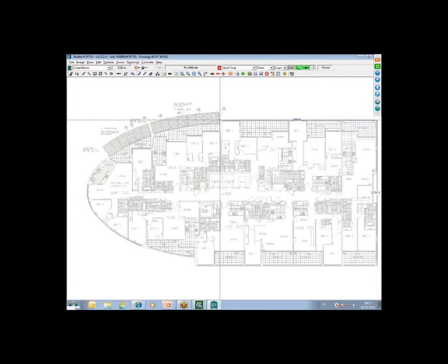I'm going to do this very quickly, and I'll just click on that line first, on that point there, and put in what the dim is on that line, and then select the vertical line, and that's just clicking on start, clicking on the end, and putting in the dim of that line. By doing that, you automatically calibrate each line that is displayed on the drawing. So it will accurately set the scale based on 2 known dimensions.